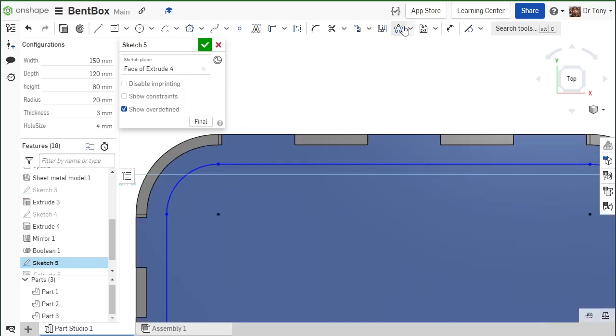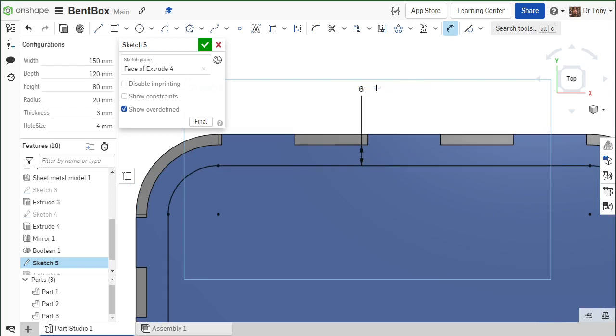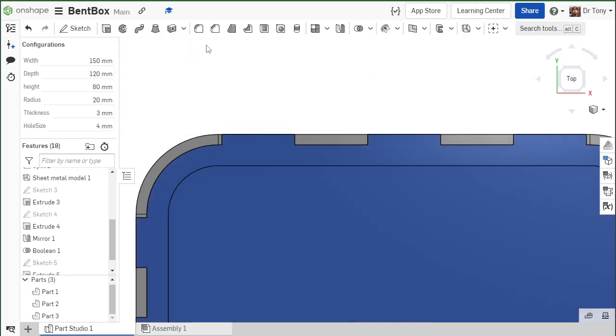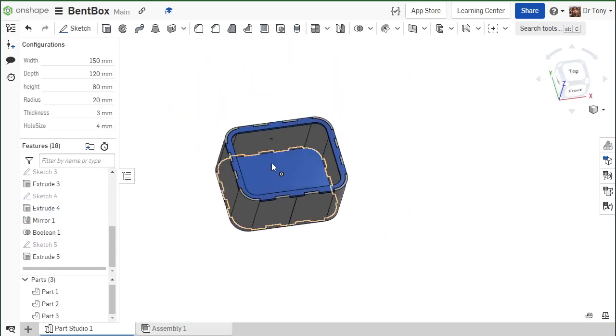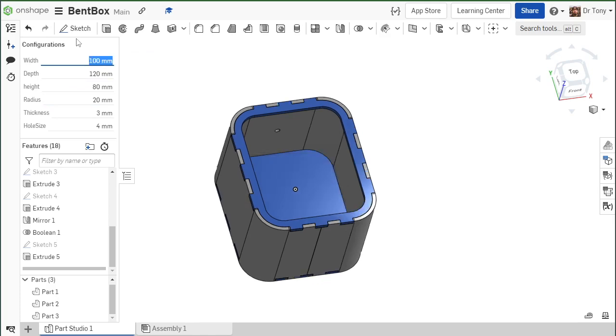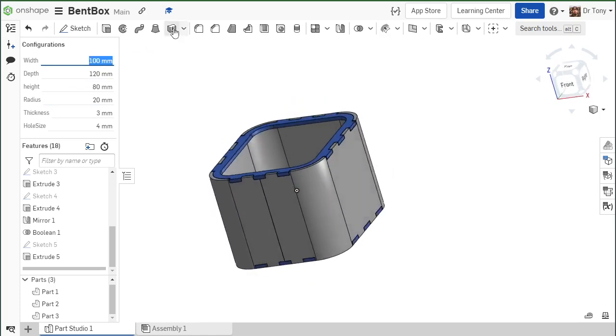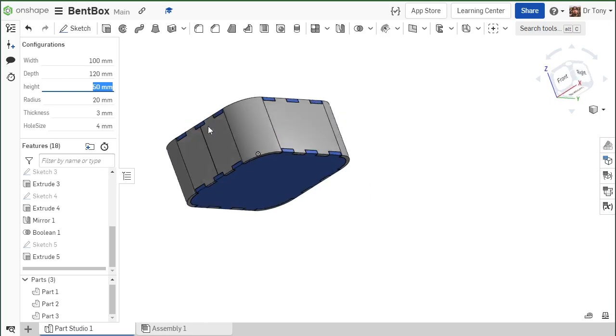Okay. And then make sure to use one of these as an anchor. Okay, so this is T enter times 2. All right. Call that good. Gonna grab it. Oh, yes, it did grab it. Cool. Sweet. Okay. So if I make this 100, it's gonna work. It works. Sweet. It rebuilds. All right. Height of 50. Everything rebuilds just fine.